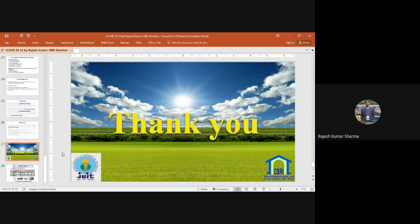Yes, we have tested for freeze thaw resistance up to 50 freeze thaw cycles, and the data are till now not finalized. That's why I'm not sure, but we have conducted a freeze thaw resistance study also. And the sulfate and chloride attack also? Yes, sulfate attack and chloride penetration attack we have also tested. Carbonation? Carbonation we have not conducted, but after extension of this project, due to COVID the work was stopped. So further we will do this.